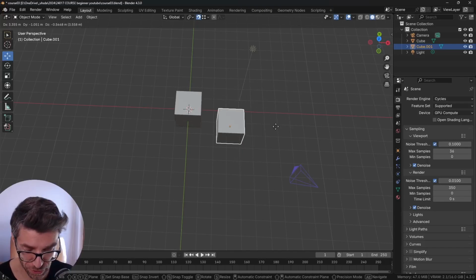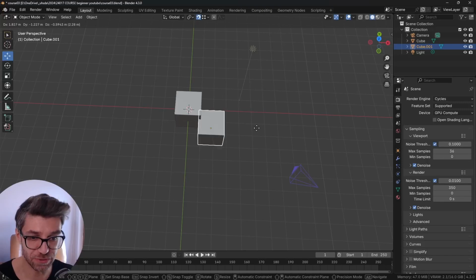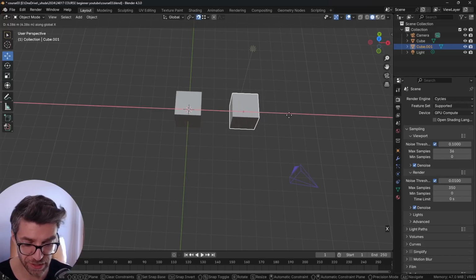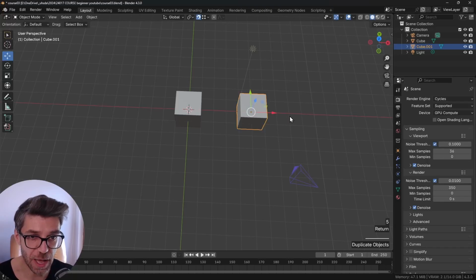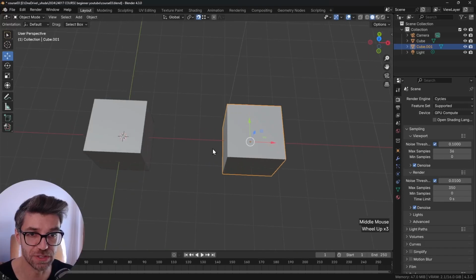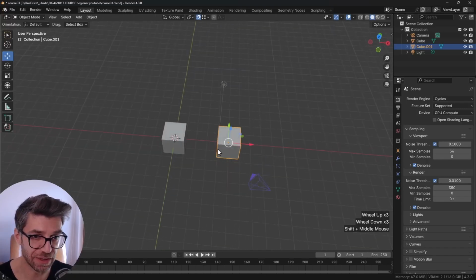In Blender, if you don't know, you can press X, Y, and Z while you're in a transform to lock an axis. And then we can type a specific number, like let's say 5 units. I'm using meters at this point, but it doesn't matter. You can use feet and inches or millimeters, and it can have the same effect.